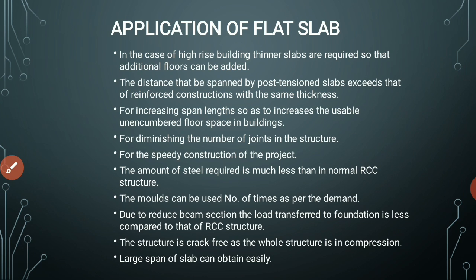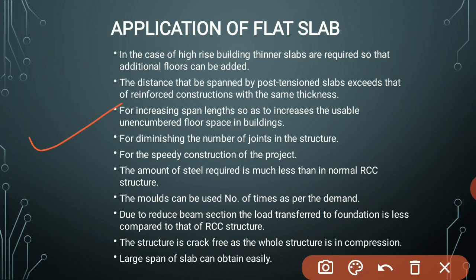Now what are the applications of the flat slab? So this is very important. In case of high rise buildings, thinner slabs are required so that additional floors can be added. If you compare with slab with beams, we have that much thickness or area or space wasted.